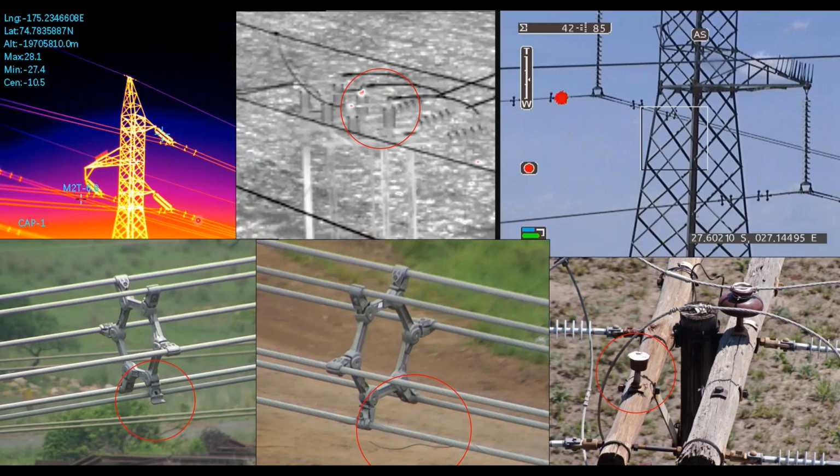During these operations, these are some of the images that we captured, and we just want to show what we get from these cameras. You get a thermal infrared, which is used to capture thermal issues, and this is still infrared, it's just that we chose different color spectrums. We also have a UV camera, which is looking at the corona issues. I think most people here will understand what corona is, but I do not intend to discuss it; this is what we use to capture that.